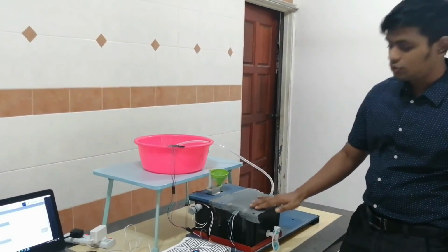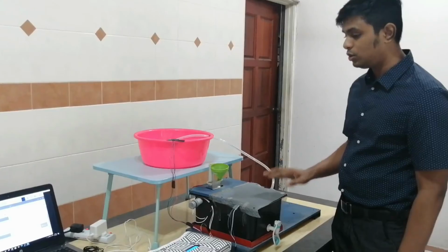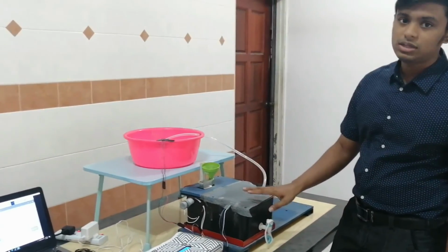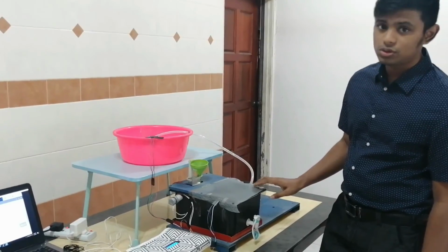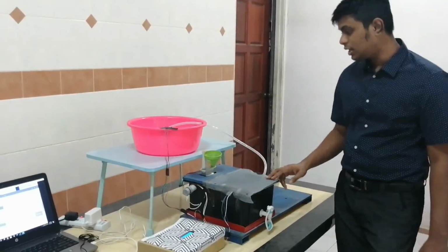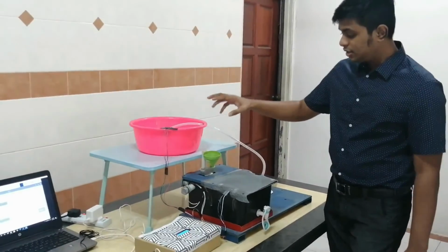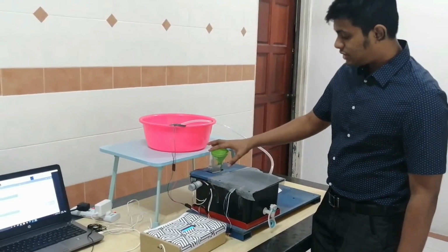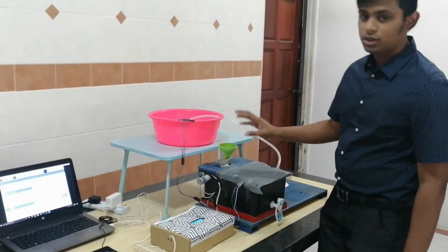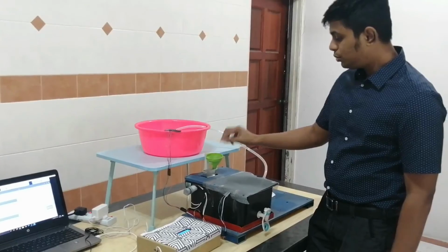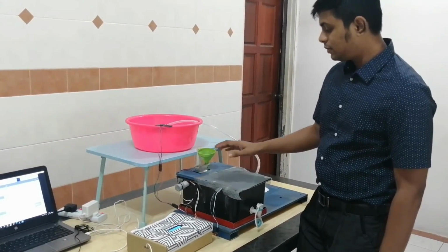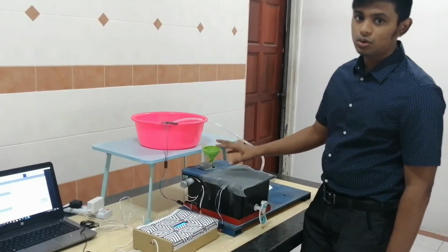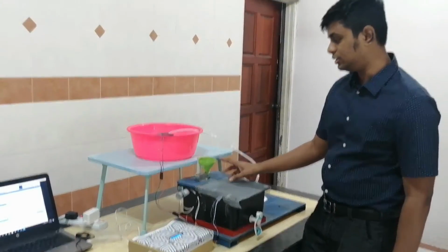Inside the sump tank are an ultrasonic sensor and a water pump. The ultrasonic sensor is used to detect the level of water, while the water pump is used to pump the water from the sump tank up to the header tank. This filter funnel design using the solenoid was designed mainly to pour Abate 1.1G into the sump tank. This is a method to control the vector reproduction.